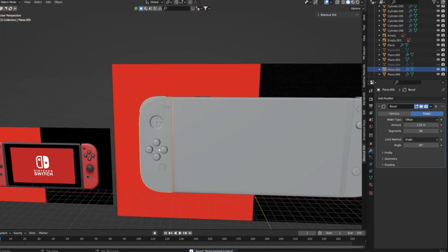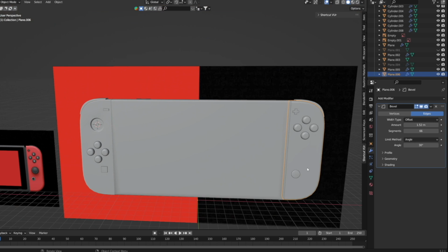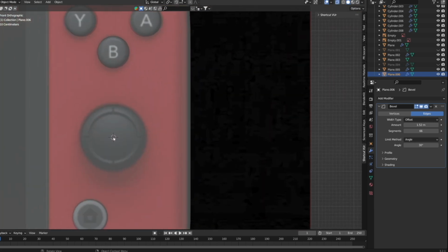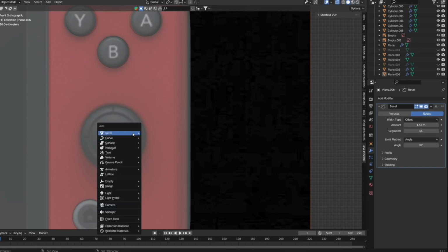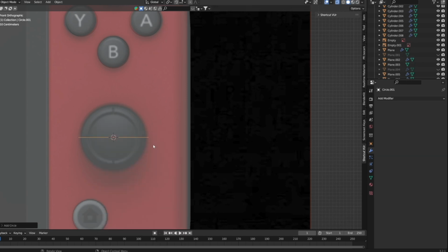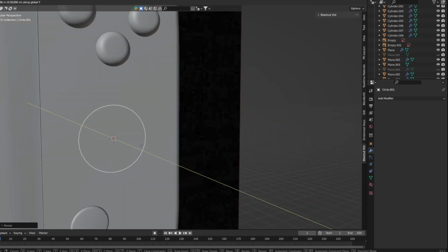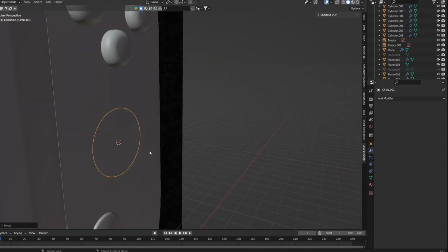And what we want to do is essentially do the exact same thing on the right hand side. So like I said previously, we will be doing the identical thing on this side. So naturally, tab out, let's get ourselves another circle, and let's rotate the circle on the x-axis 90 degrees, and let's zoom this down, put this into correct position, and let's bring it outward. Let's move it outwards just a little bit, not too much of course.